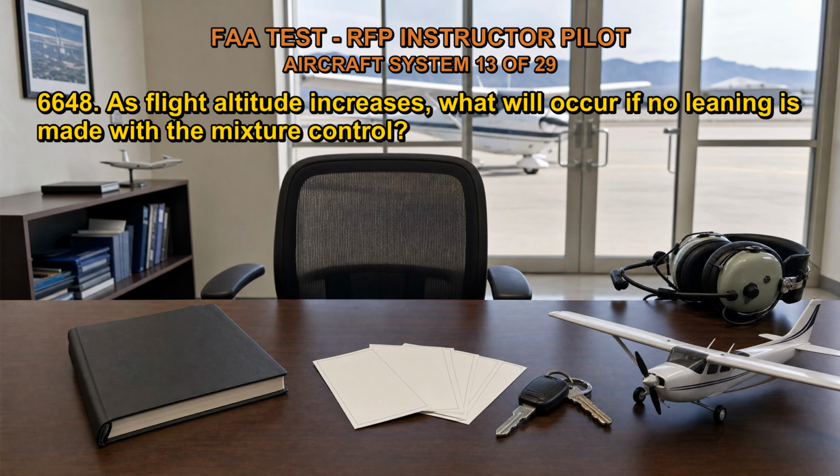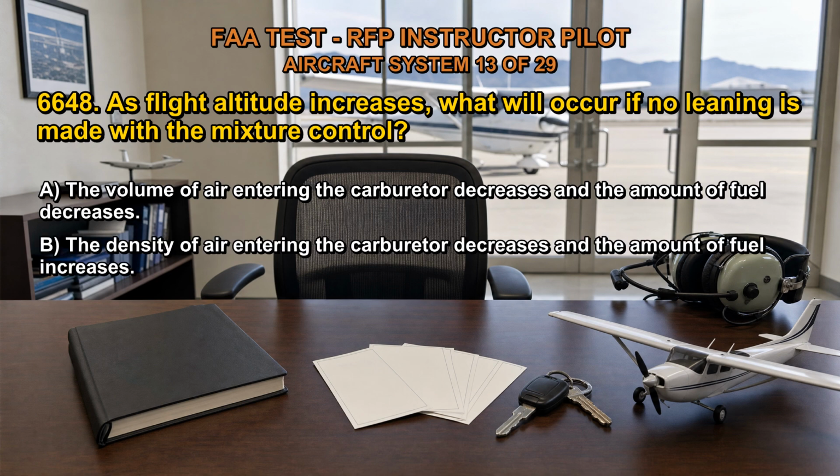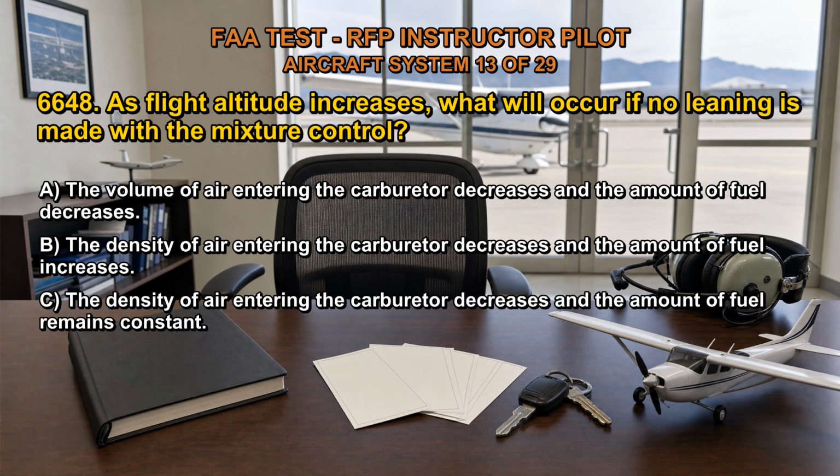6648. As flight altitude increases, what will occur if no leaning is made with the mixture control? A. The volume of air entering the carburetor decreases and the amount of fuel decreases. B. The density of air entering the carburetor decreases and the amount of fuel increases. C. The density of air entering the carburetor decreases and the amount of fuel remains constant.